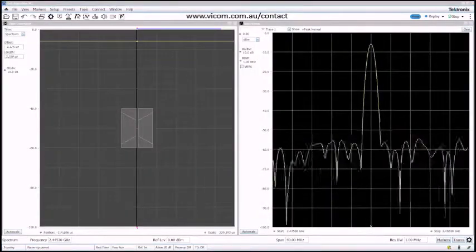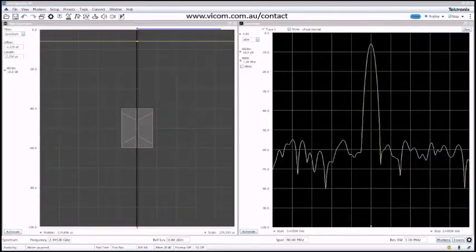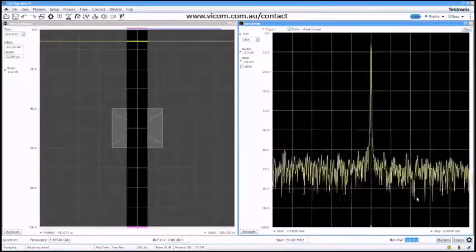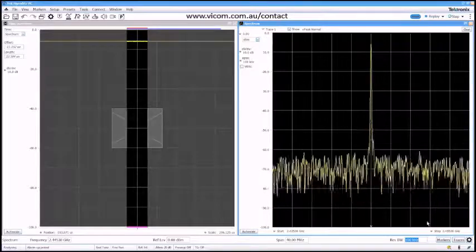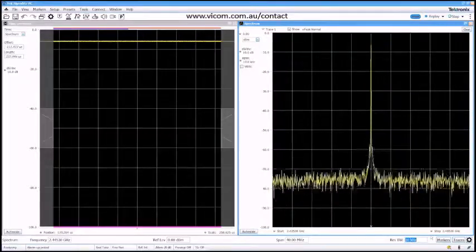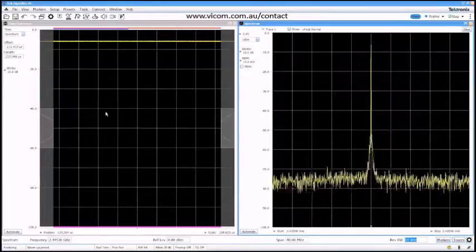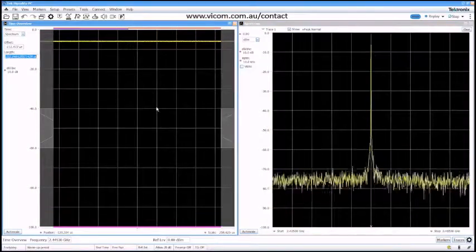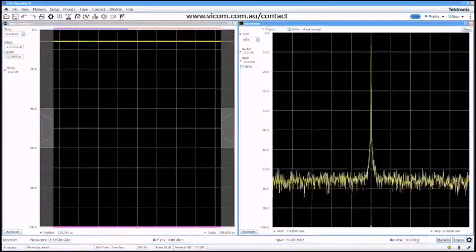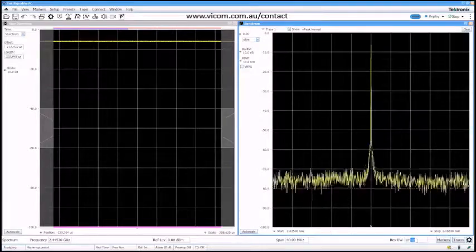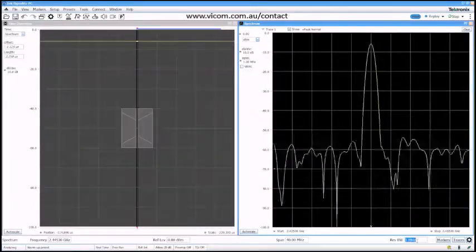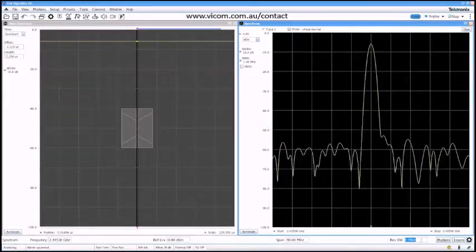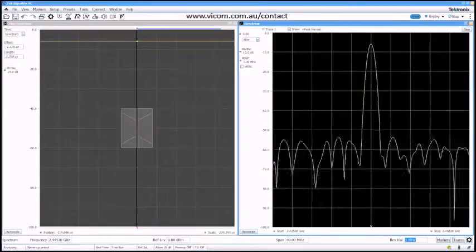Narrower RBW values result in longer capture times. The analyzer needs to capture at least as much time as the period of the RBW frequency to resolve that small of a frequency separation. The capture time is usually longer because the window factor needs to be taken into account as well. By default, Tektronix RSAs use a Kaiser filter shape for the RBW, which has a window factor of about 2.23. This means the analyzer has to acquire 2.23 microseconds of time to resolve a 1 MHz RBW.